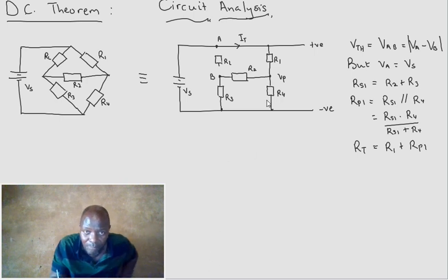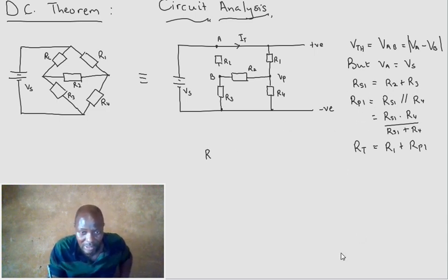It's equally easy to have said, I have got R1, R2, R3, which I was given in the circuit. So I could have worked out R parallel. R series 1 I have, and R parallel 1 I have worked out already. I don't have to work it out again. I already have R series 1, which is R2 and R3. We have worked out R parallel 1, which is these two in series but in parallel with that. So we've got a value for R parallel 1. So I could have said, instead of going through the other method of IT, I know voltage already.